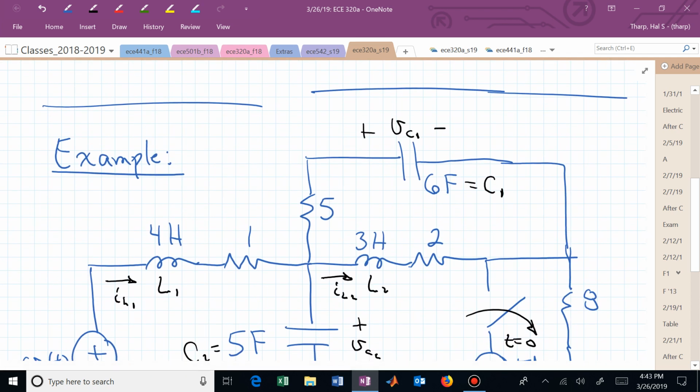Yes, there was. What happened to that? If the capacitor opens up, how much current is flowing through that 5 ohm resistor? 0. So we could put it in there and we'd have 5 times 0, and it won't matter. So we could worry about the drop across that 5 ohm, but there is no drop because it has 0 current flowing. Does that answer your question?